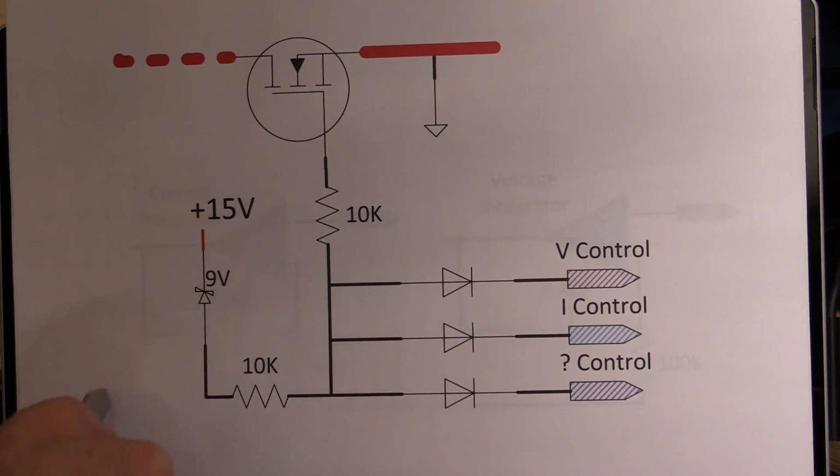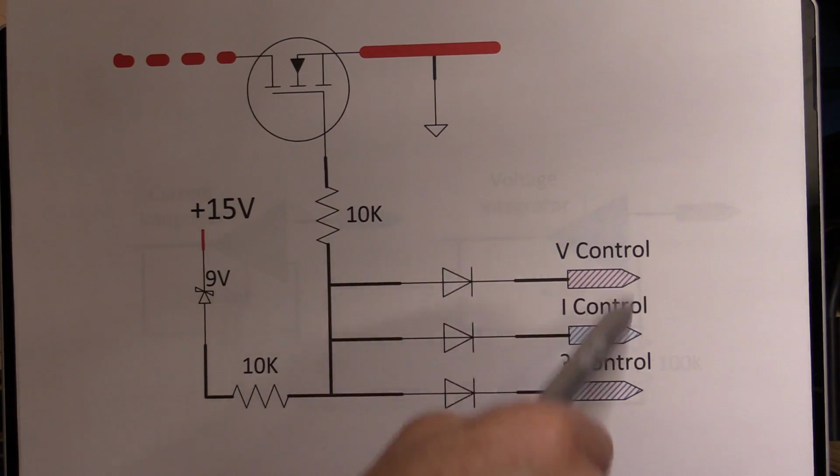It's very easy to create a little resistor divider to set some kind of threshold, whereby until your charge circuit, and you can use a little RC circuit from your 5-volt reference or something, is charged up, it says, oh okay, I can release control and allow the power stage to be driven. This could be just a comparator, not an actual closed loop control. So it's either flat high, really high, or really low. As soon as this goes really high, it will release control and allow these other two to take control of it. And as I said, you can put as many of these on as you like. It's a very simple way to drive that output stage from as many different control circuits as we want without having an issue.